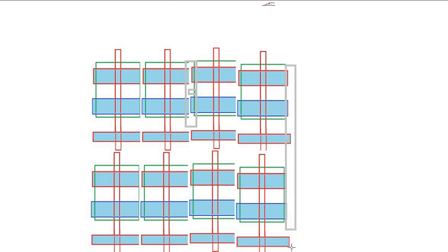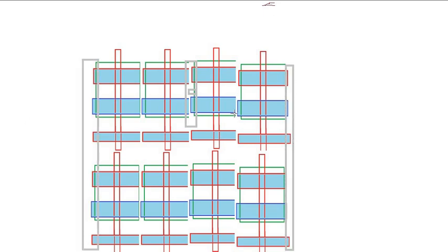Generally, in standard cells, you end up drawing it at the edges like this. Or whenever you want to detour a signal over here, there is a continuity here, for example, and you want to make a connection at this point and this point. So you draw a cut layer here, and I'll draw another cut layer here. Depending on whether I'm using a red color cut or a blue color cut, we have color coding for cut layers also, right? So then you have the flexibility of making connections over here.